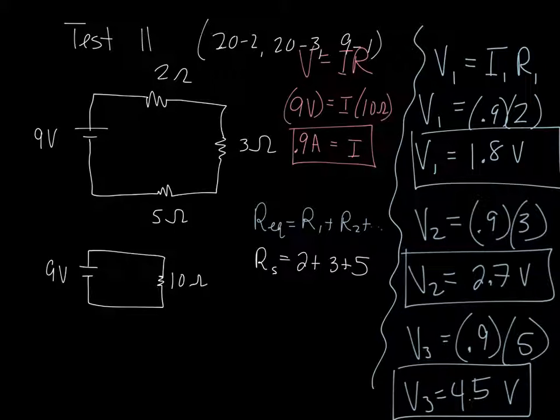Recognize that your resistance is a pretty large value. You added them together. Because the resistance was a large value, the current was a very low value. Resistance and current, it's a balance. They're inversely related. Very good, Tom. If you have a lot of resistance in the circuit, your current has to be low. If you have low resistance, which we're going to see in a minute with parallel circuit, the current is going to be really high. Okay? So this was our summarization with series. If you can do an example like this, you should be relatively good.